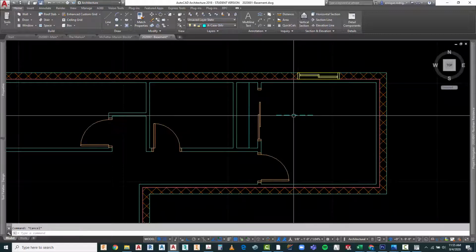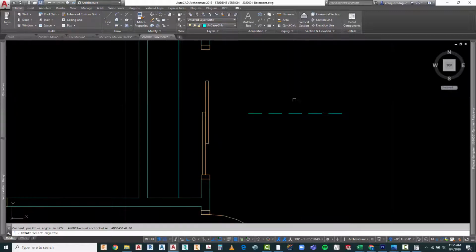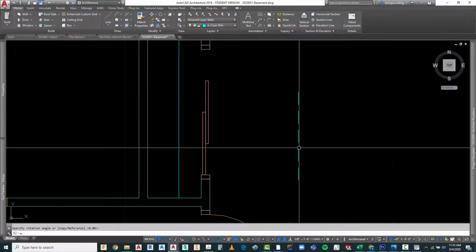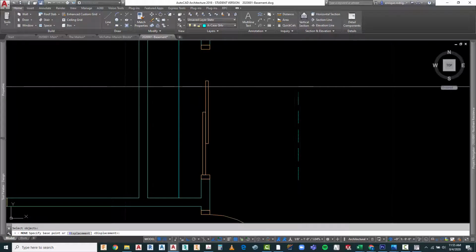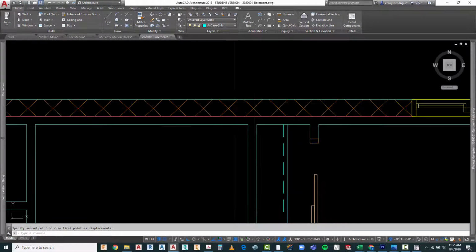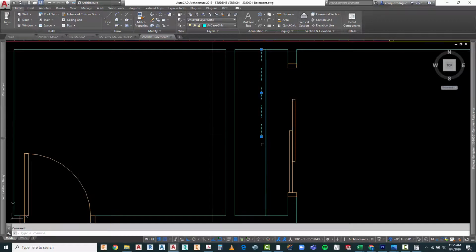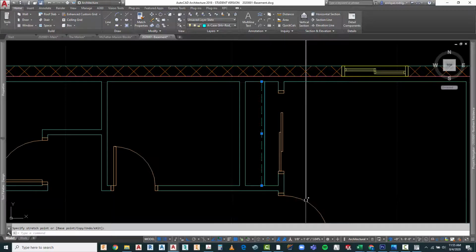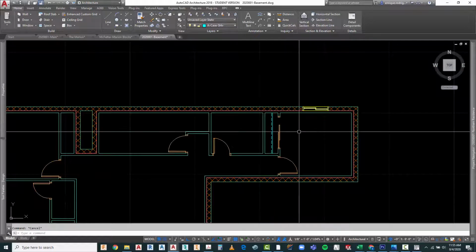So there's a multiple number of ways to get this to work. So I'm just going to go ahead and rotate this and move this guy over from there. This one I'm going to put right in the midpoint there, and I'm going to grab it by its grip, and just go to midpoint or perpendicular at that point. So I've got that one located.